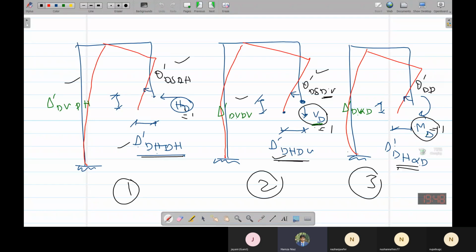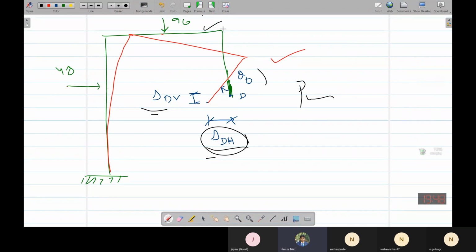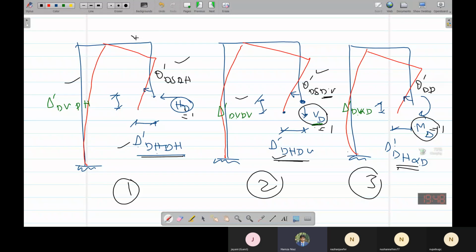It was simple: we calculated the moment at this primary structure, then the moment produced by the unit force, put it as m m over EI, and integrated it from 0 to L, where L is the limit of the part of the beam or frame for which we are finding the deflection. This is the deflection formula. Remember it? For beams and frames.